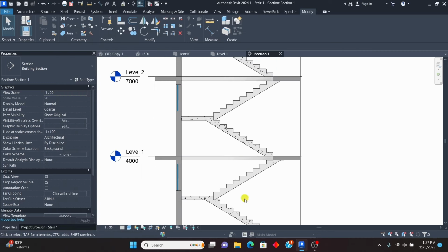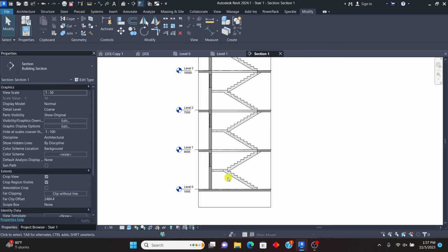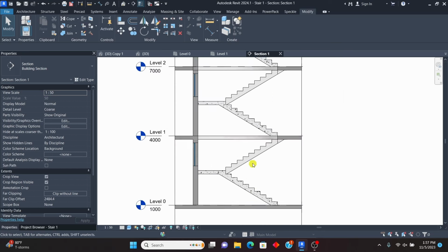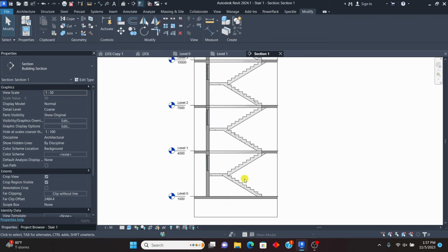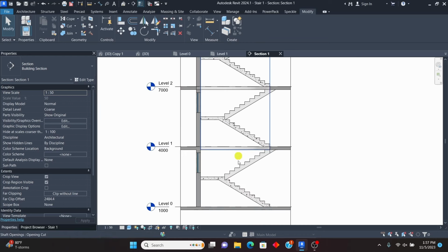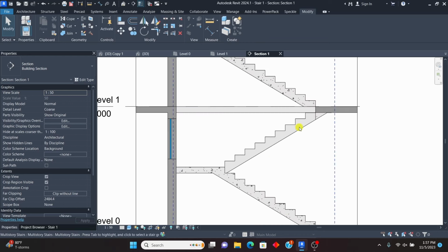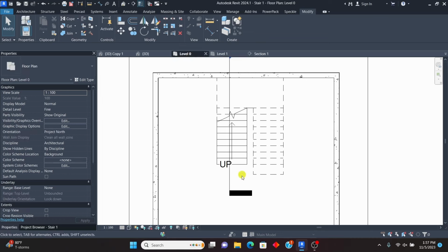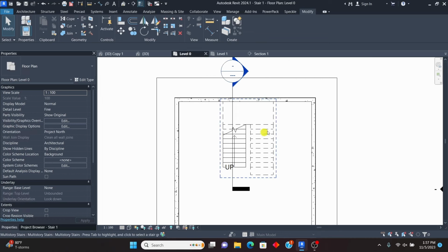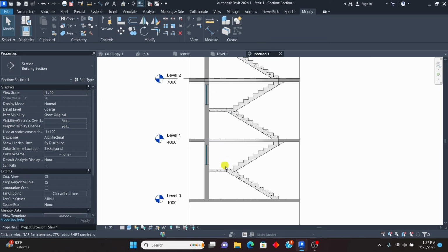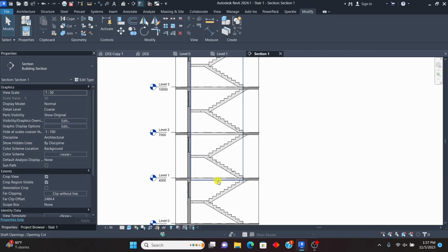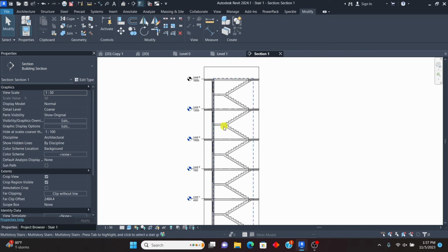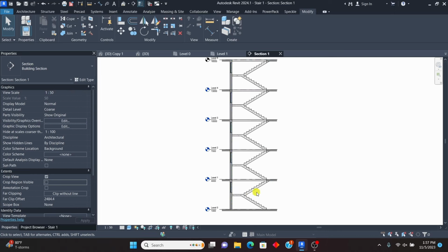Click OK. Now you can even see that here it's not cutting. We are somewhere here, we are cutting there. So this is what I want to see. Okay, and I'm happy with what I have. You can even see that we are cutting a section here. Here we are not cutting according to what we have here. The section is cutting here, it goes here, it's not cutting. So it's okay. All these things can be changed if you so wish. Now the other thing is that I just need to hide the box outside here by deactivating it from here. This is part of detailing now.